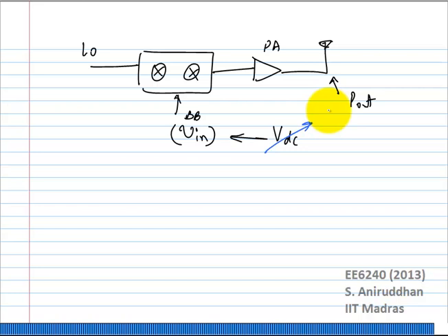How do I do that? What decides that value? Correct. So what you really need to do, the output power is really a function of the RMS value of the signal going into the baseband. RMS value of the modulated signal going into the baseband. Okay. Now the peak power at the PA output will be related to the peak, right? The average power is related to the average value going in.